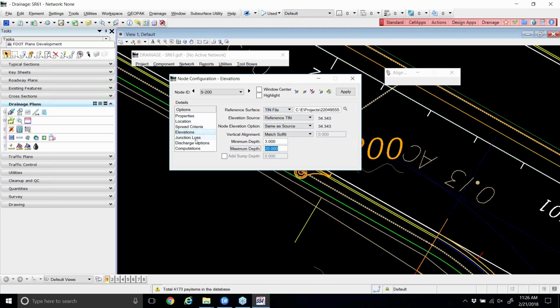On the junction losses, what this will do, if you flip over to the top of 420, this allows you to specify different methods for calculating junction losses, or different junction losses for that particular node if needed. That is not usually going to be needed, because that's why we have that whole drainage library out there. So you're going to leave it toggled on, just like is shown in the book here, to defined equations. So you probably won't ever have to change any of that.